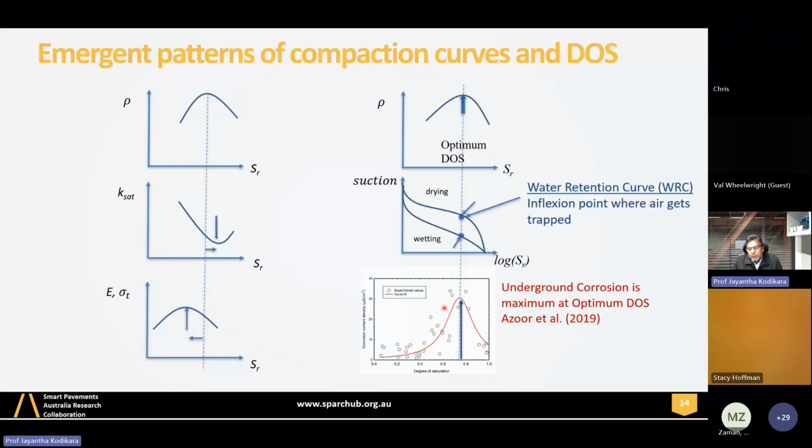And a very interesting thing we have found is also when you bury a metal pipe in the ground, if you compare to the optimum conditions, which is normal geotechnical practice, you also maximize the corrosion potential, right? I don't have time to go through why that happens, but this point has optimum moisture and water availability.